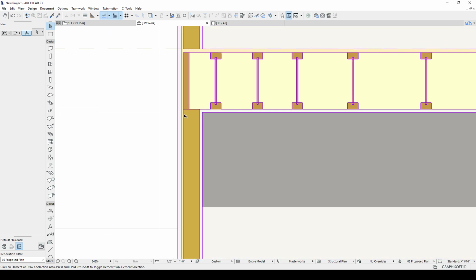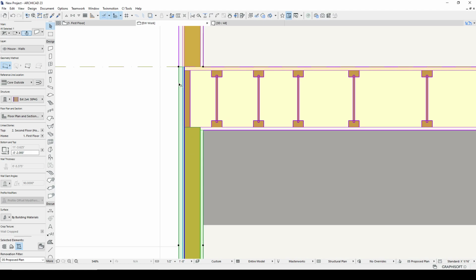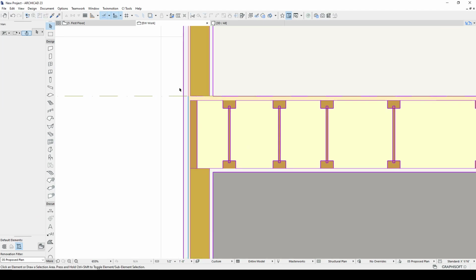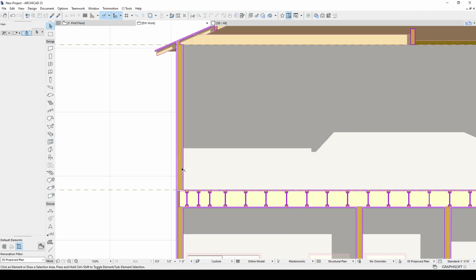Up here, we're running the wall all the way to the top of the floor, second floor. And because of the floor that is modeled here with the plywood, the gypboard, and the framing space, it's doing something similar. So we're getting the stucco running all the way through without having the break in the floor. And it represents how we actually build our homes when we stick frame.